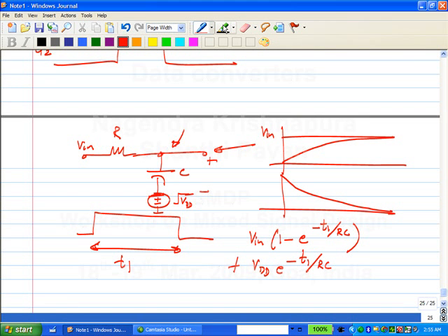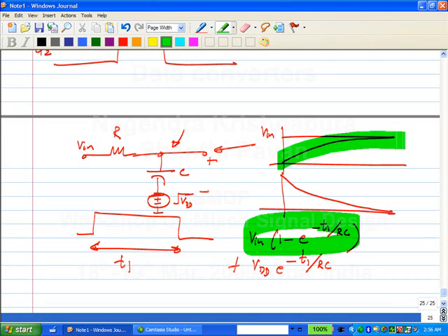But what you have actually done is you only have now a fraction of Vn, because this has not reached the full Vn yet. That might not be too bad, but there is a worse thing happening, and that is it has not yet forgotten VDD. What was there? The last one. You understand? Correct?